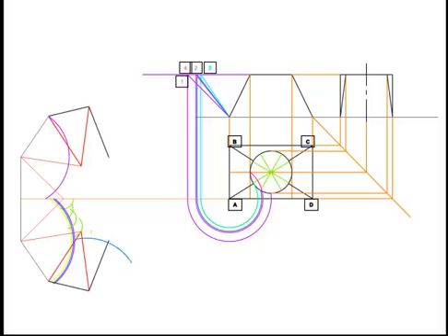We can then do the same process over again beginning with the blue line, which is got from this true height here and swung from this point here this time, and again the same distance within these 2 green sectional lines, or this arc, to locate our point. Same process again like before, and now we can join up these points.